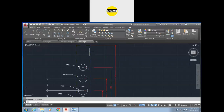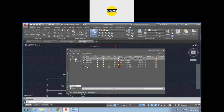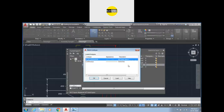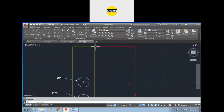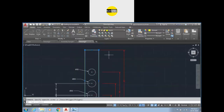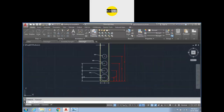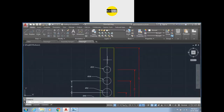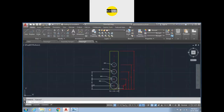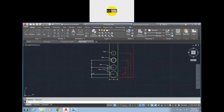Now you can see we have applied a line type to the geometry, and I want to change it. So go to the layer properties, and you can see that in geometry you have applied the ISO line type. I'm going to select the solid line, close. Now you can see we have the solid line here. To add a reference, suppose I want a line here, and I want to create that line as a reference or center line. So select that line, go to reference, and you can see that the line type is now a reference line. So in this way you can apply the layers.